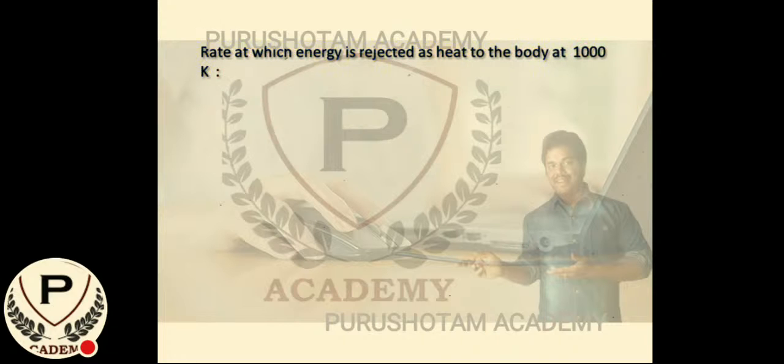And coming to the next one, rate at which energy is rejected as heat to the body at 1000 Kelvin. Okay, so we have to find out Q4. So we know that work done by refrigerator A, WA equal to Q1 by COP of A. Okay, as we know the value of Q1 is equal to 1 and COP 1.21, substituting the values, that equal to 1 by 1.21, which is 0.826 kilojoule per second.